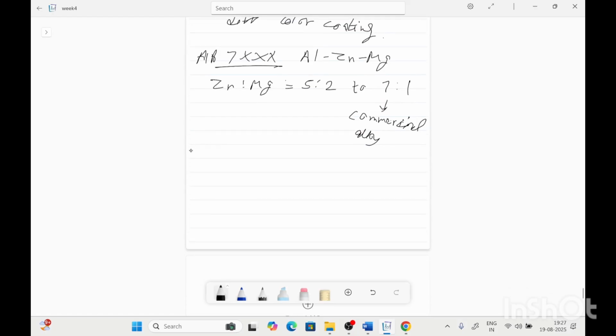So the sequence of the GP zone formation and precipitate in this is: the supersaturated solid solution forms first the GP zones, then eta prime precipitate will first form, that will change to eta. So the eta is the equilibrium phase. So this has the MgZn2.